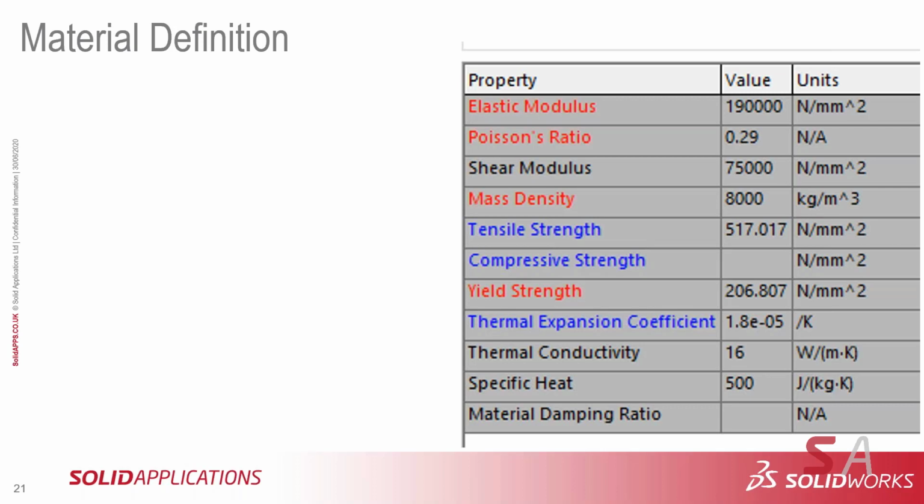Wow, okay, good. Now, density, that's another one. Density is not needed for a linear stress strain study. It doesn't enter into the calculation. It matters if you're going to apply gravity or if you're going to apply a centrifugal load. Suddenly, now density is important. It matters if you're going to go into Simulation Professional and do a buckling study or a frequency analysis. Yeah, or a drop test. Now density plays a very important part, right? But for a plain old regular, I'm going to bend this bar study, no, density is not crucial until you're applying gravity. All right, so you don't have to have density unless those types of forces are in your study.